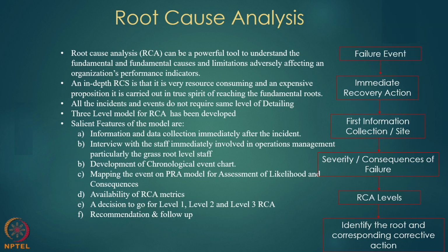Okay, so as I was mentioning in this slide, I will just give you an overview of root cause analysis. First we see that the failure event has happened, then immediate recovery is required, and then the first information report. The first information report is very important, because if you don't have this report, much of the information will be missing and later will not be available. Then assess the severity of the consequences, and based on that we have to devise what kind of root cause analysis is required.